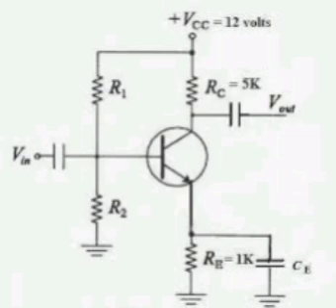Describe the construction and working of a shunt type ohmmeter. Write down its design equations. The circuit diagram of shunt type ohmmeter is shown in figure. Here E is in series with R1 and a switch. Parallel to R1 and the switch is Rm. The current is Im. The inward current is I1. Outward current from the node is Ix. That output parallel resistance is Rx. AB is connected, taken as Rx.